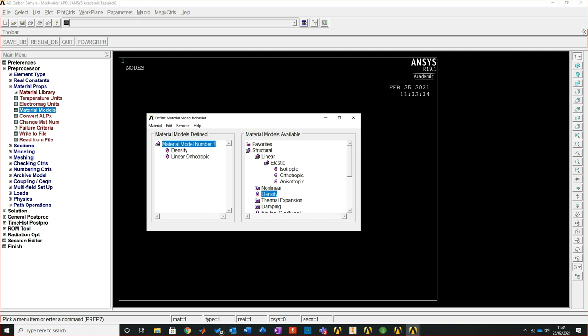Making an edit to a material when you come back, I would always recommend that you delete that material and then make a new material again. This system does not like you going backwards. It's been the biggest criticism for years, and this is one of the reasons why they introduced Workbench, because Workbench essentially bolted to the front of this and it did all these little bits in the background for you. Made life so much easier, so much easier. In many ways you just felt a bit spoiled because it was like, yeah, it's doing it all for me, which is great.